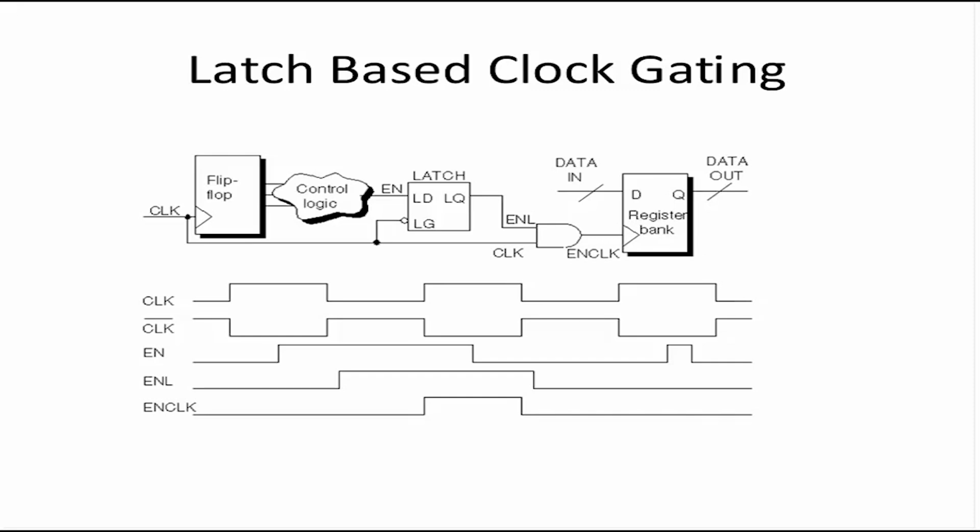For a particular type of clock gating, we use a particular type of latch. Now let's look at this figure. In this case, the clocks are positive edge triggered, and now we want to use an AND type of gating. This is where the gating takes place. This is the gating cell. So enable signal and clock are gated to provide an EN clock. Now the mux at the data input is removed. The enable signal, instead of going to a mux, goes to a latch. The clock goes to a latch.